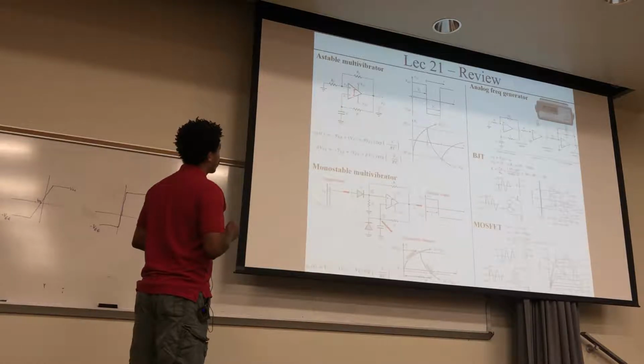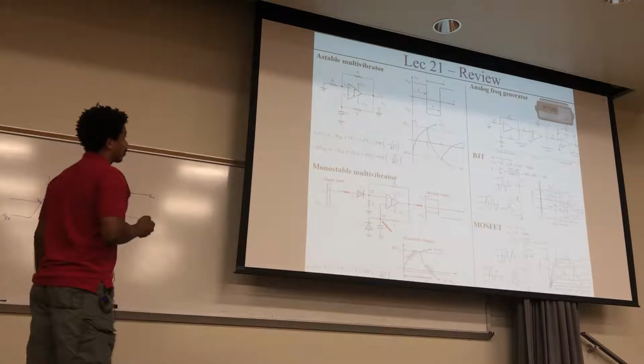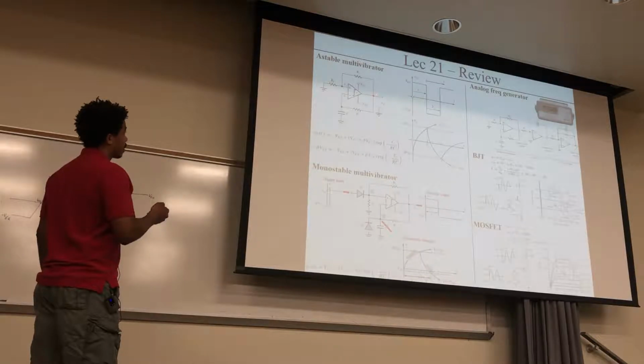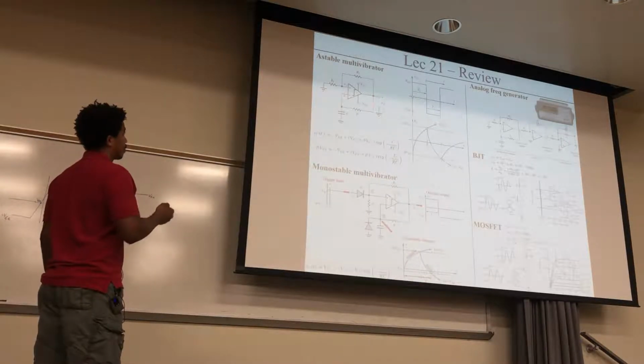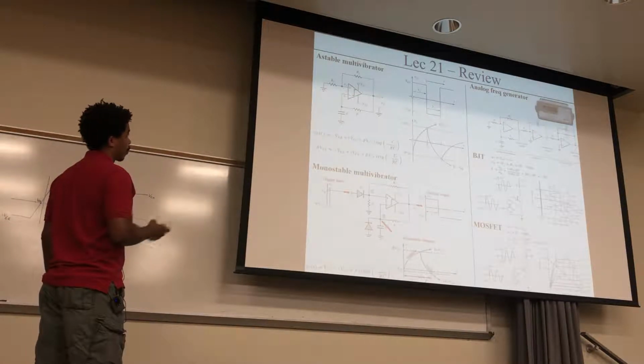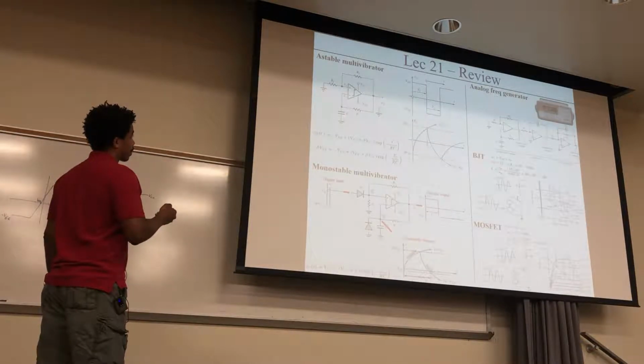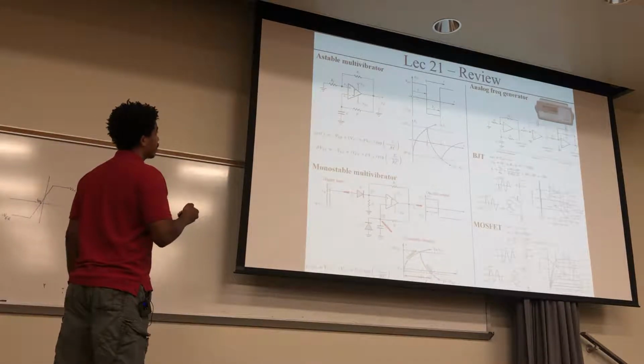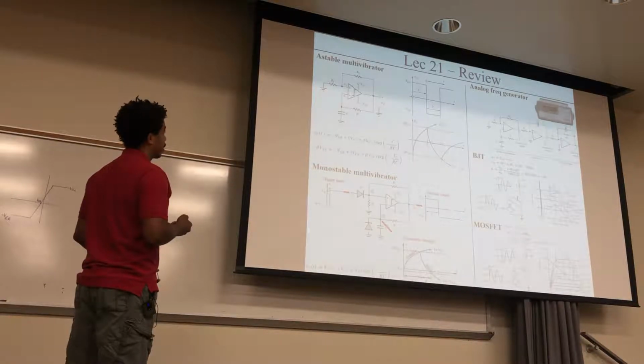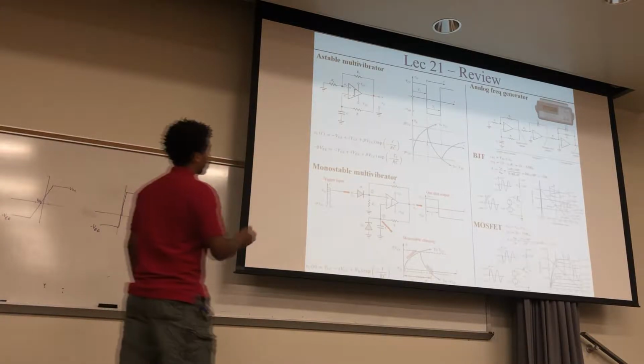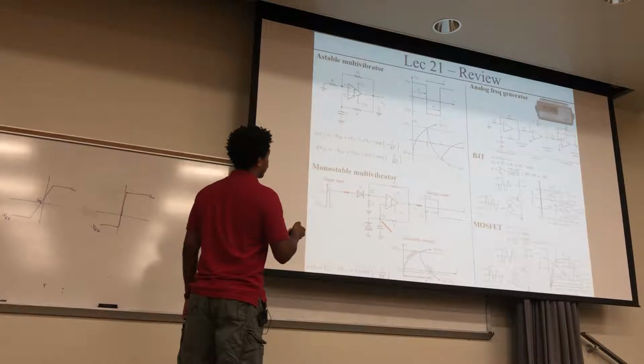That tendency to saturate very quickly, either high or low, allows this to turn into an oscillator, because you can use the saturation voltage out here and feed that back to change whether this saturates high or low for the next state. This capacitor is put in here to allow some time to pass before it switches to the other state, because you have this RC time constant. Here it's saturating really high, here really low, but this time right here has to do with the RC time constant.